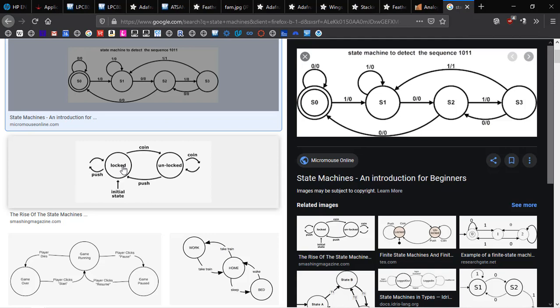Now you could also envision that you maybe have a flashlight that's got 3 or 4 buttons on it, or a dial on it, that it has multiple control mechanisms. So it's got more than one input or output. But a flashlight, a modal flashlight, is a great example of a one input, one output system, where a state machine can help you figure out how to write the code correctly rather than trying to figure out all the combinations of ifs, thens, and elses from first principles.